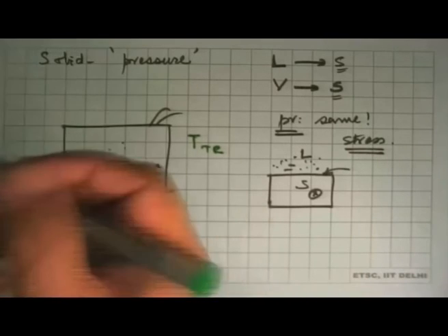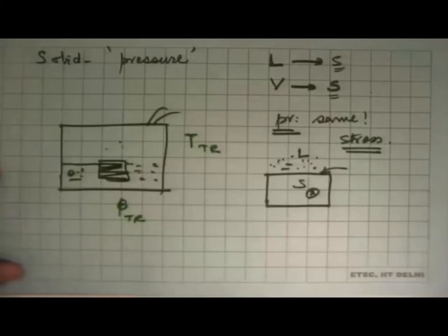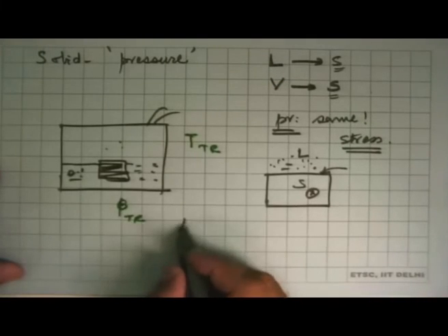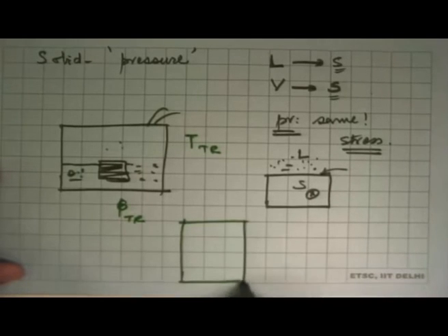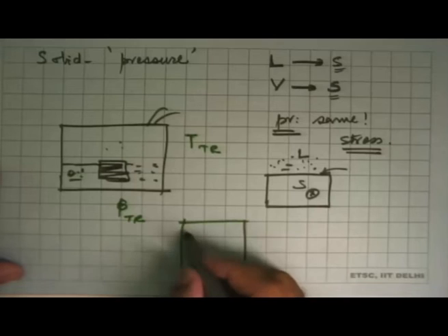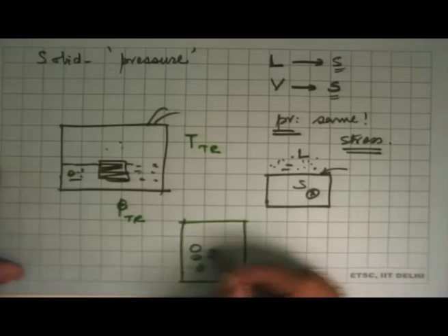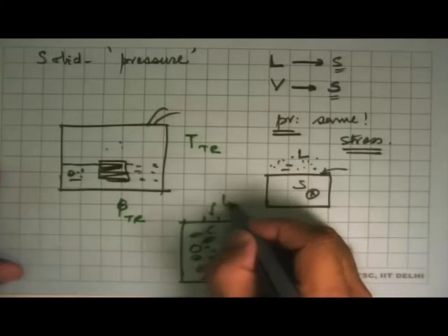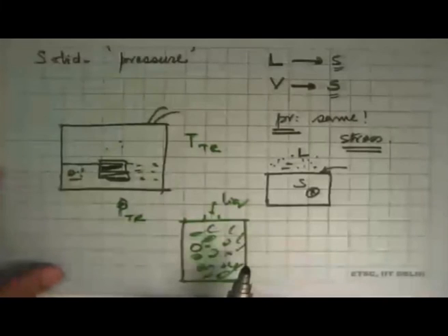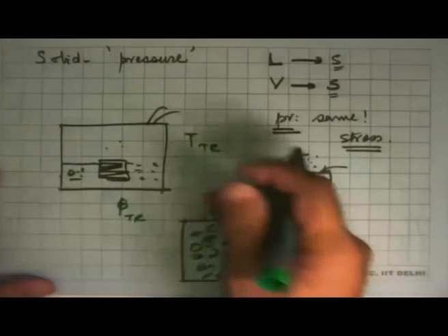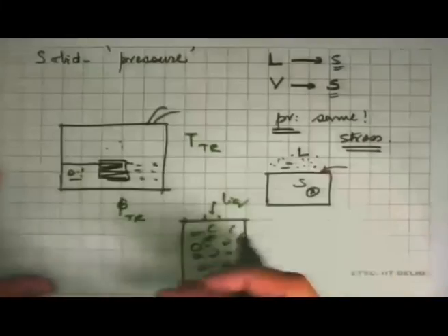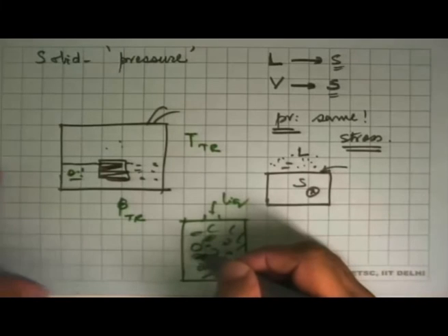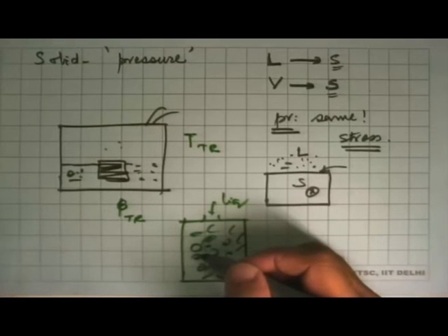And we exploit this in one very important way, not in thermodynamics but in all measurements of temperature, especially in heat transfer. What we can do is, and you can do this small experiment yourself, take a thermos flask, push crushed ice into it, pack it as much as you can, and then pour a little bit of tap water in it. What will happen? The temperature of the water, which was say at 25-30 degrees Celsius, will go down, some of the ice will melt, and if you keep measuring the temperature by putting an instrument in this, you'll see the temperature going down. It will start going to 3 degrees, 2 degrees, 1 degree.